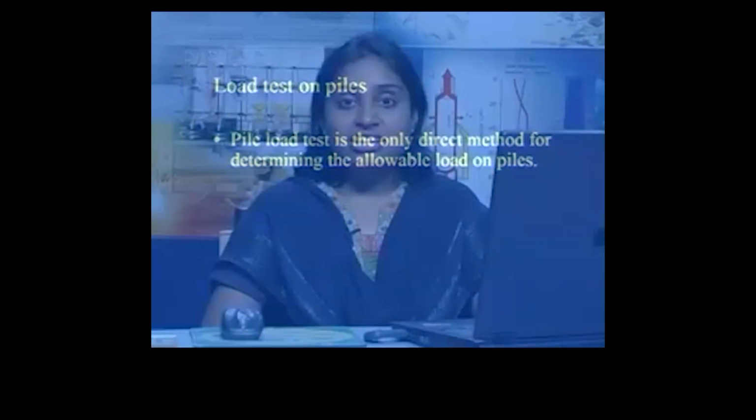You have seen that in case of static pile load formulae, first we computed how you can find out unit skin friction resistance, and then skin friction resistance by multiplying that unit skin friction resistance by the area on which it is acting. Then we found out unit point bearing resistance, and when we multiplied that by the base area of the pile, we got point bearing resistance of the pile. We summed them up and then we got the total ultimate load carrying capacity of the pile.